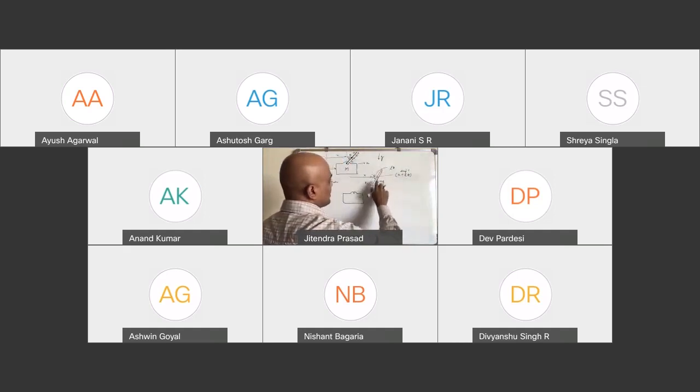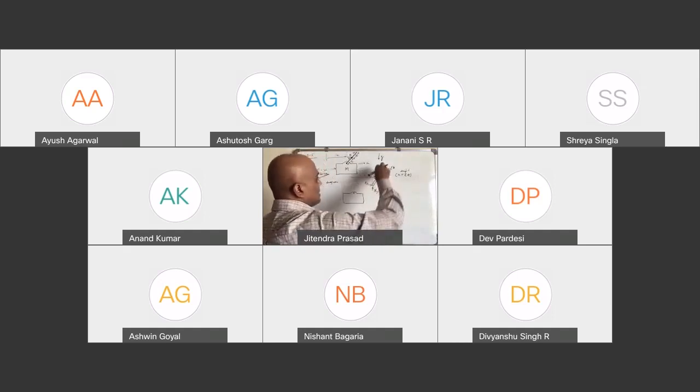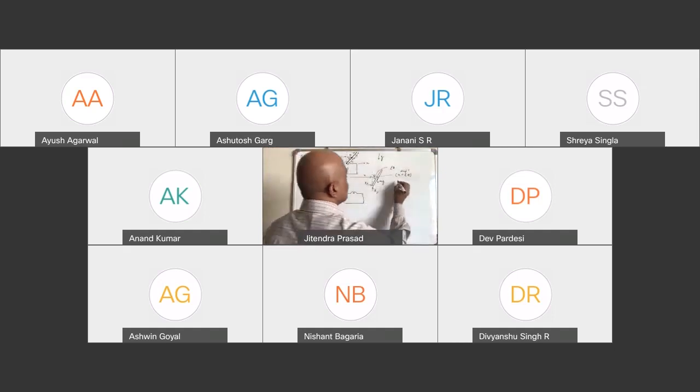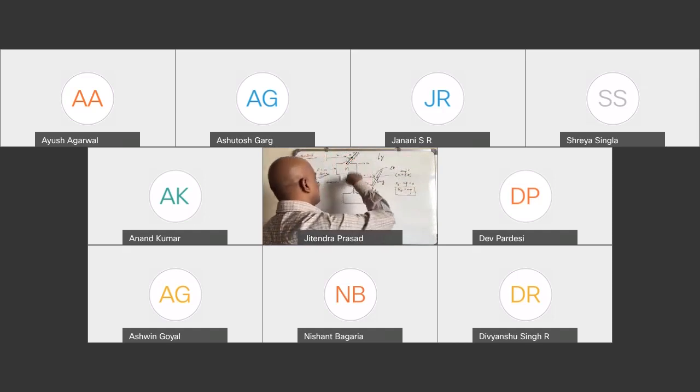But the forces, what do we see in this case is since it is vertical and not moving very much, the vertical location remains the same. That really means there is no vertical acceleration, and hence you can say Ry minus mg equal to 0. So simply you get Ry equal to mg. Whatever force is applied here, the same force has to be there. So mg goes like this.